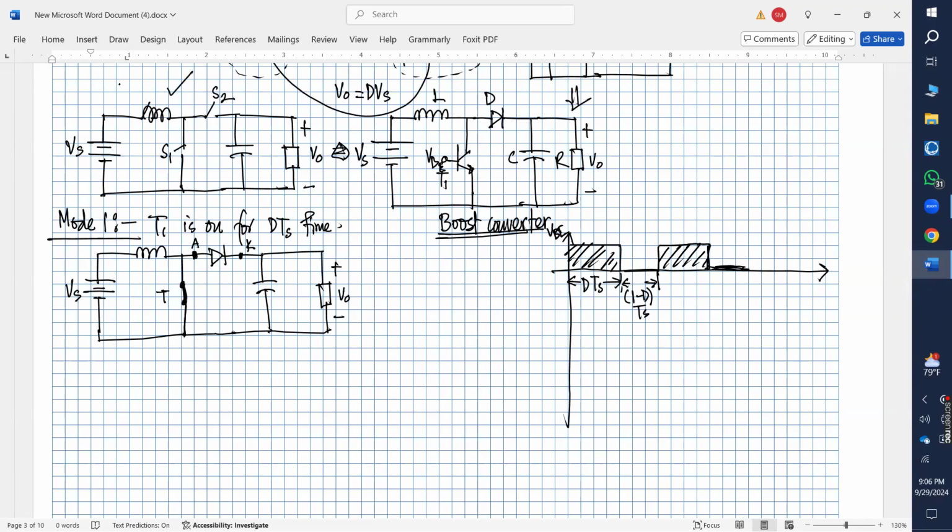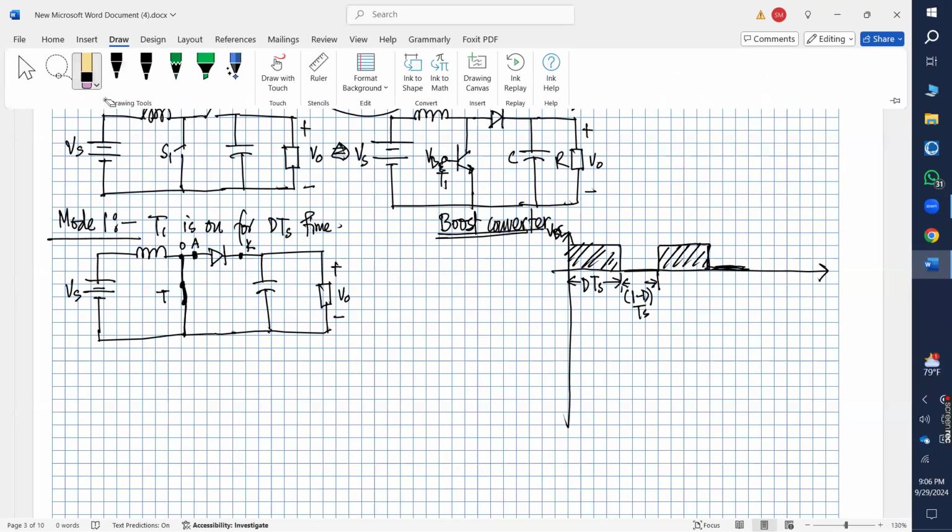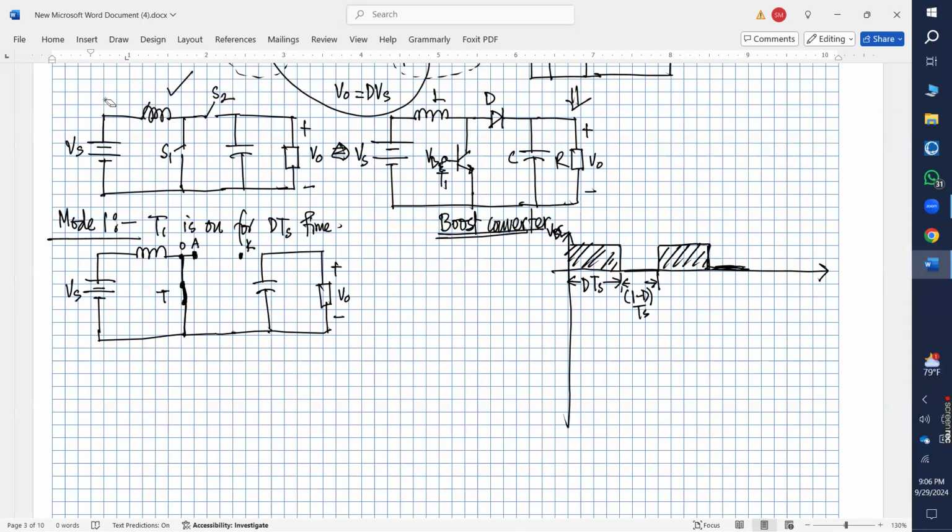So this is short circuit. So the potential here would be 0, right? And the K terminal is connected to plus V naught voltage. So should this diode operate or will it be reverse biased? Reverse bias. So practically, this diode will not operate.